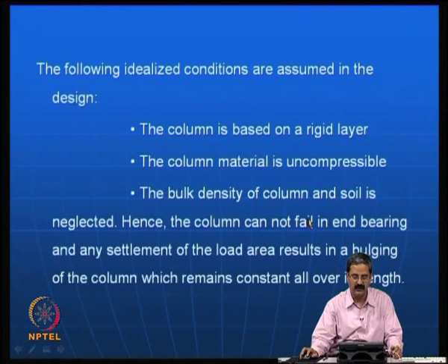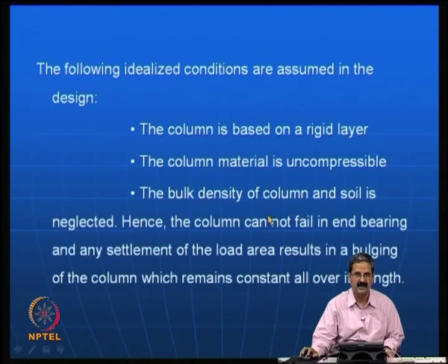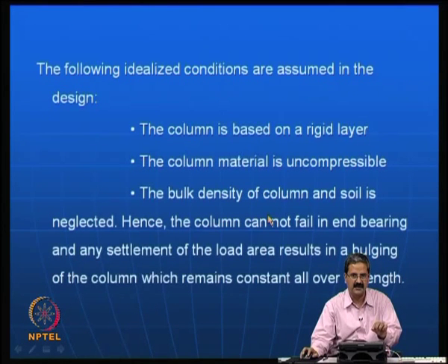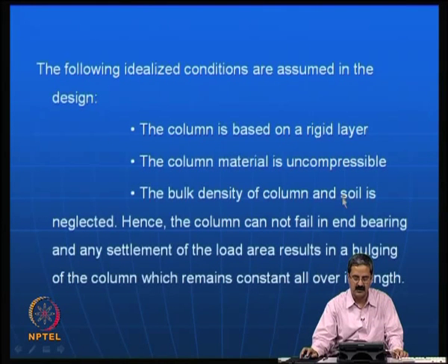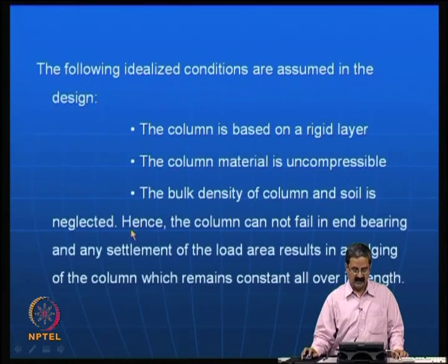It comes later in some form, but these are some of the assumptions. We make some assumptions and we propose a theory, and we correct for all the small things which are supposed to be critical. Since the bulk density of the column and the soil are neglected, the column cannot fail in end bearing, and any settlement of the load area results in bulging of the column which remains constant over its length.